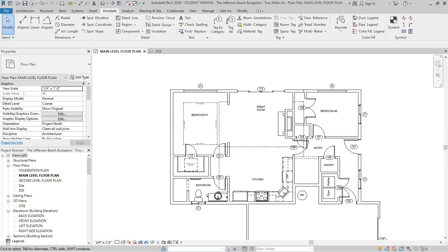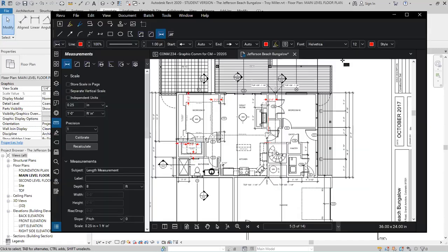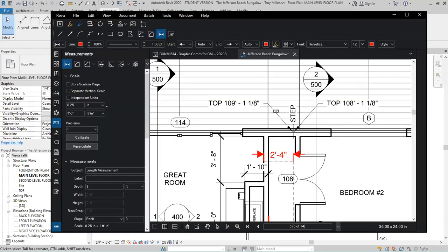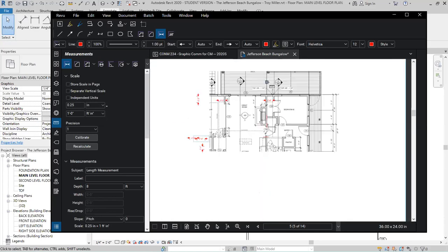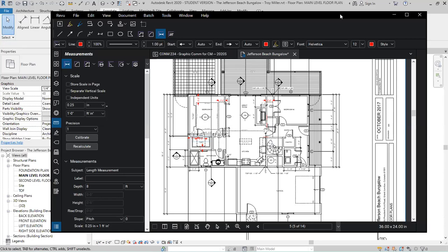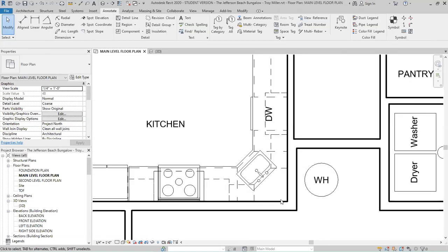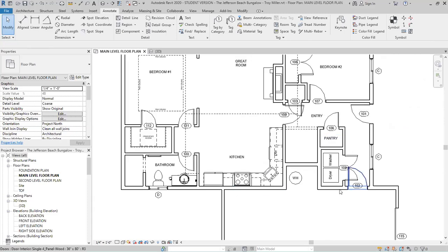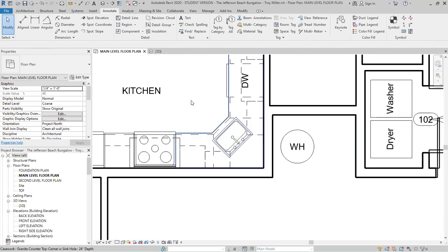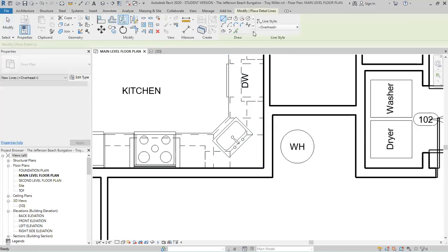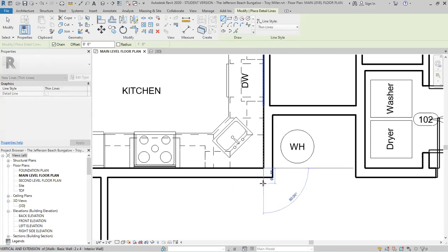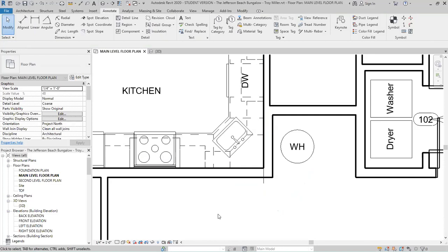So we're just cruising right along here. What I would like to do now to finish this video is actually 2 more things. We need to put dimensions in there, but before we do dimensions, I want to mark where our 2 steps are. Now I'm not sure what quite happened over here because the step in the wall disappeared on me, even though we know that that step is occurring at this location. So I'm going to cheat the system here. I'm going to go to Detail Line, select a thin line, and just put in a line right there.